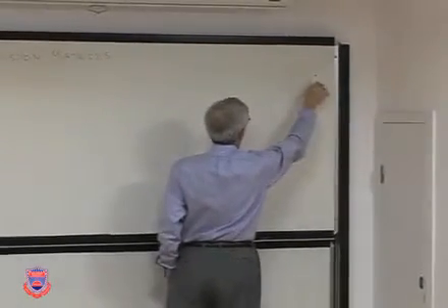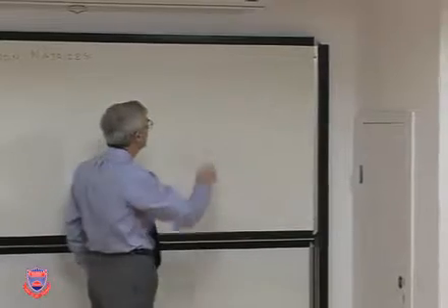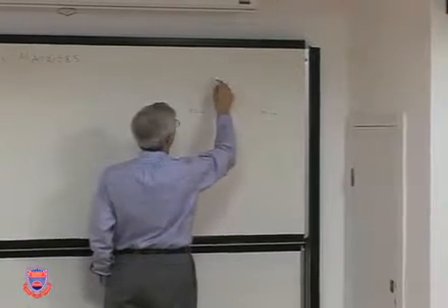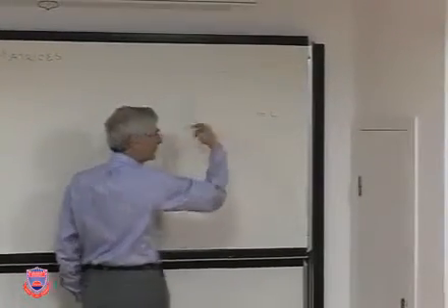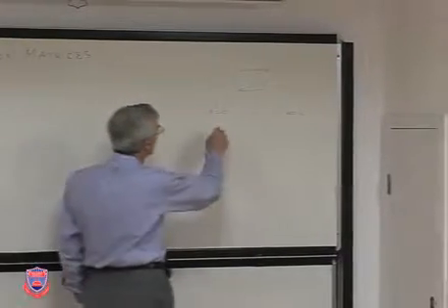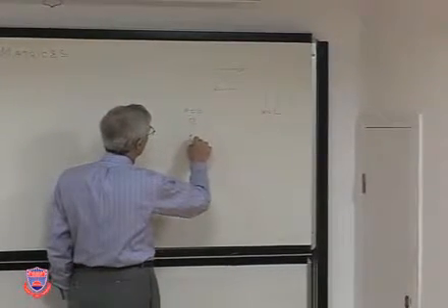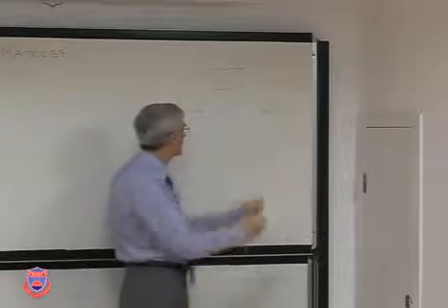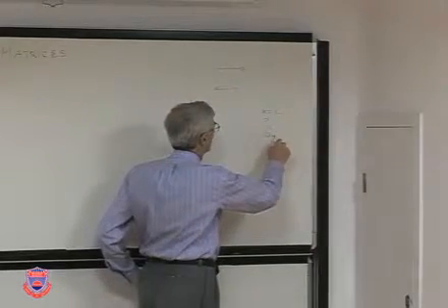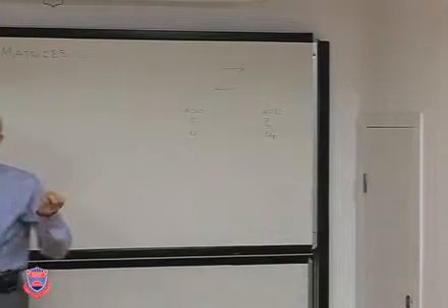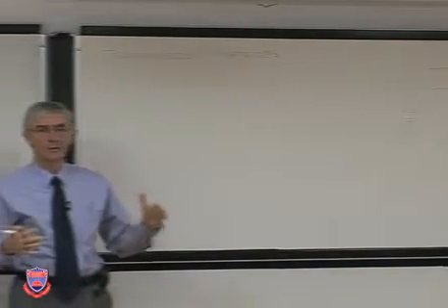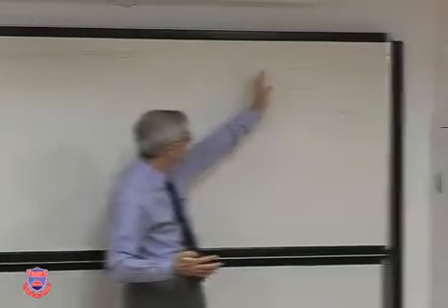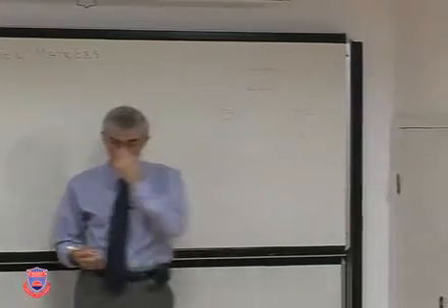Now, what we mean by transmission matrix is, if you consider a medium where sound is propagating back and forth, and let's just consider arbitrarily two boundaries in which sound is traveling back and forth. And then we call, let's say, pressure and particle velocity P1 and U1 at one point, and pressure and particle velocity P2, U2 at the other point. What we want to find out is some sort of a universal relationship between pressure and velocity at one point and pressure and velocity at the other point.